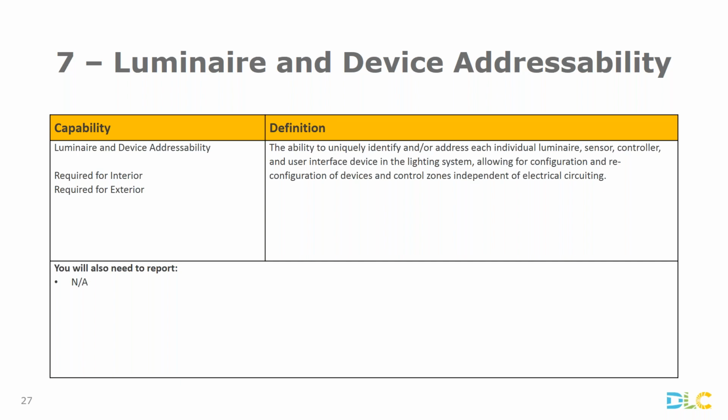So the point of confusion is that we have a number of manufacturers that are offering these individual fixture controllers that are also offering traditional zone-based controllers, made to control a group or zone of luminaires, where you would actually define the groups or zones of luminaires by the 0 to 10 volt wiring. Systems that offer both those individual luminaire controllers as well as those zone-based controllers are acceptable. And I think there are absolutely some use cases where you want to be able to offer that zone-based capability. So that's something I wanted to mention here.